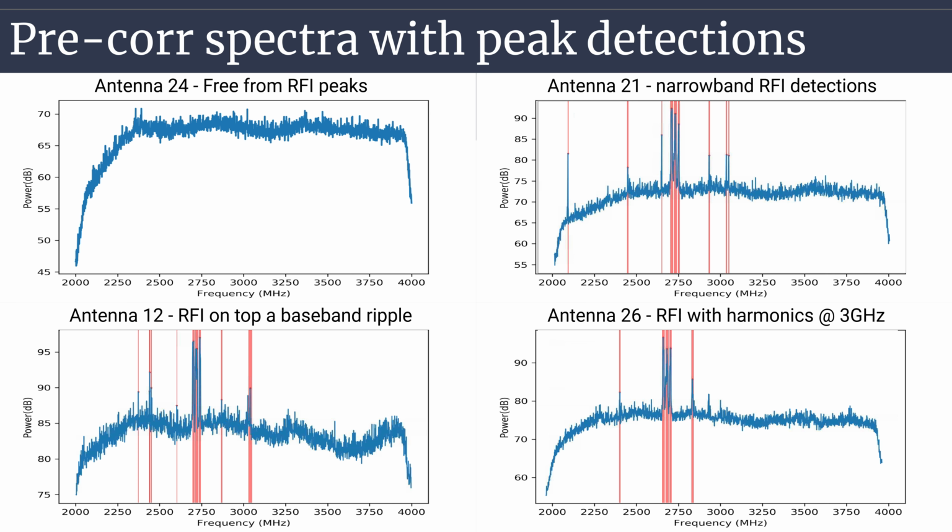The major takeaways here are that flagging pre-correlation could require better clock accuracy, and this may be a motivating reason to sample the data streams at the correlator level. And then the spikes that we're seeing in these voltages aren't showing up in the visibilities post-correlation. We suspect this is due to the decorrelation of RFI, and this is a topic Urvashi Rao is currently working on to answer this very important question.